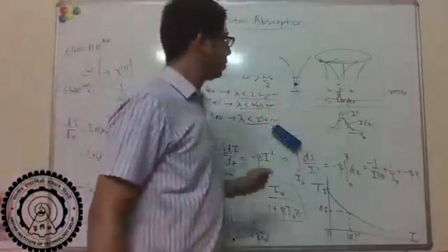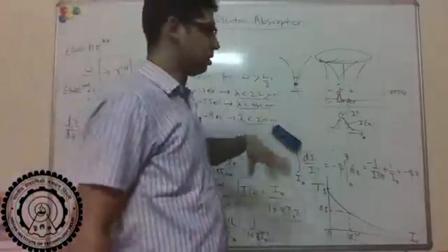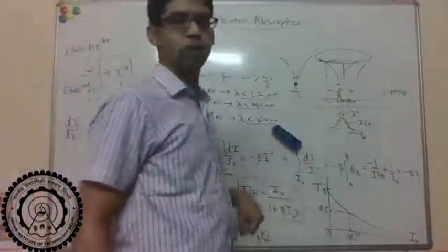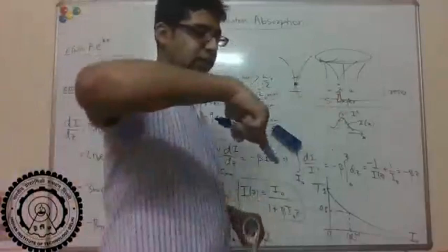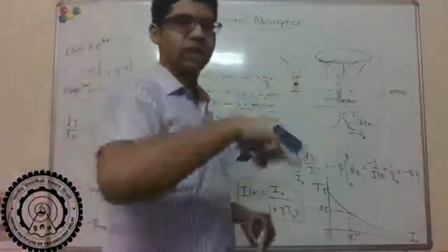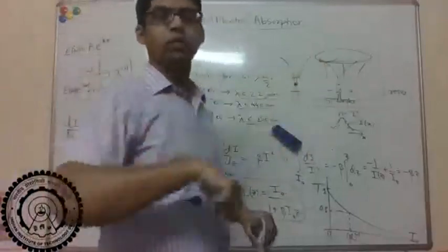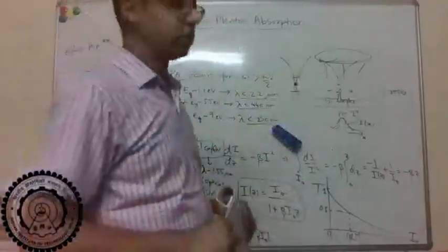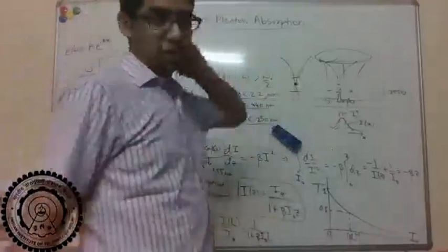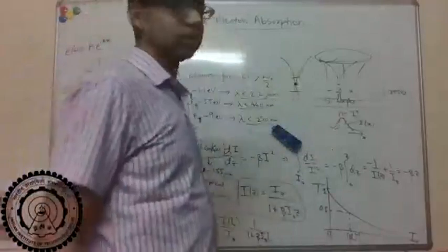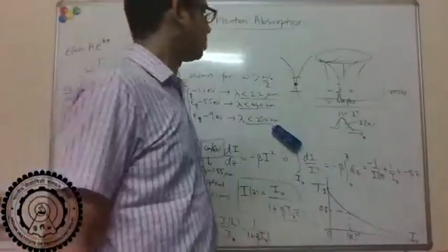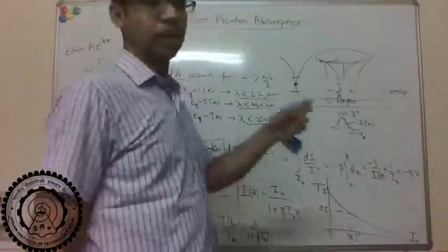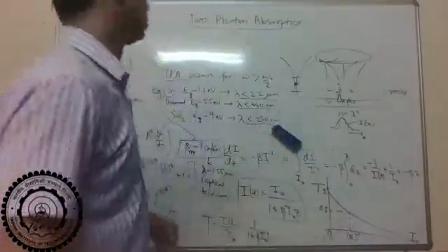So people can actually make very fancy 3D structures using photolithography. You take a laser beam and you scan. It's like 3D printing. You scan it in whatever structure you want, and then dissolve away the resist. I'll post some very nice papers on this. You can really make very complicated structures with very good 3D resolution.